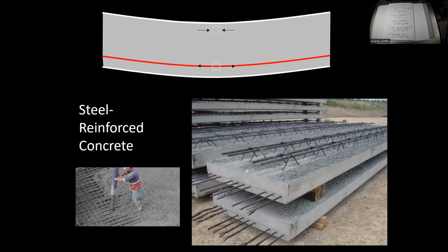This is the solution. Because, okay, so let's say you try to create a floor. So we're back 2,000 years ago with the Romans trying to build a floor. And this floor wants to bend like the smiley face. You guys see that? Which is okay for the top section. Suppose it's like a meter thick. It's okay for the top section. That goes into compression. Concrete's okay with that. But look at the bottom part. The bottom part's going to go into tension, isn't it?